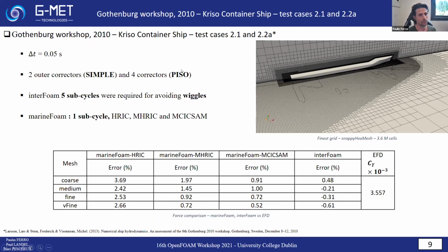So we have 2 outer correctors and 4 correctors. And as we previously saw with interFoam, we must use 5 subcycles in order to avoid wiggles. So the calculation time with interFoam will be larger than with marineFoam. MarineFoam uses only 1 subcycle and 3 VOF schemes.